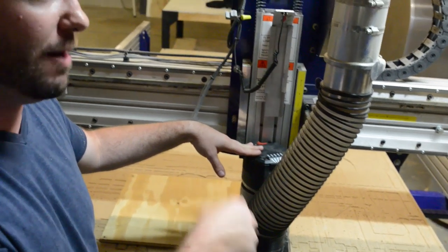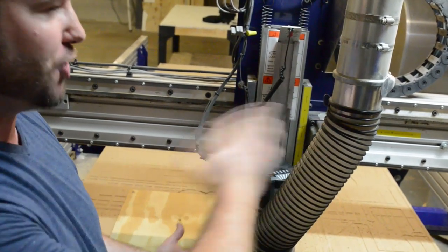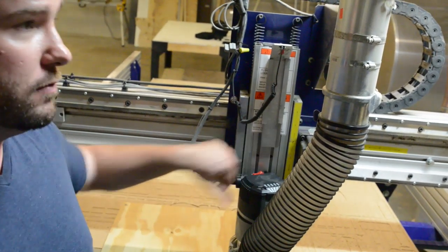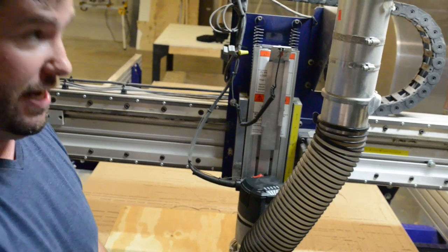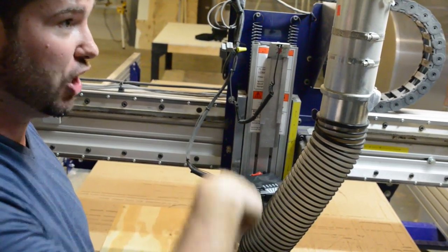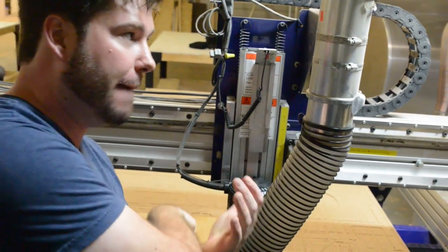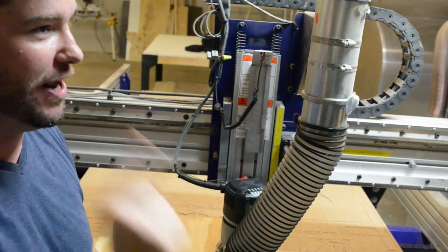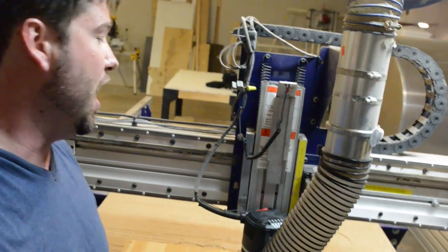So someone came by and for safety reasons, while they were probably changing the bit, turned it off just to be safe. But keep that in mind. If I would have left this off and pressed enter and wasn't paying attention, it would go through its tool path and start cutting. And without that bit turning, it would have dived into a piece of wood and probably snapped off your bit. So when you press enter after this screen and you don't hear it, you start seeing this move and it's not making a lot of noise, stop.